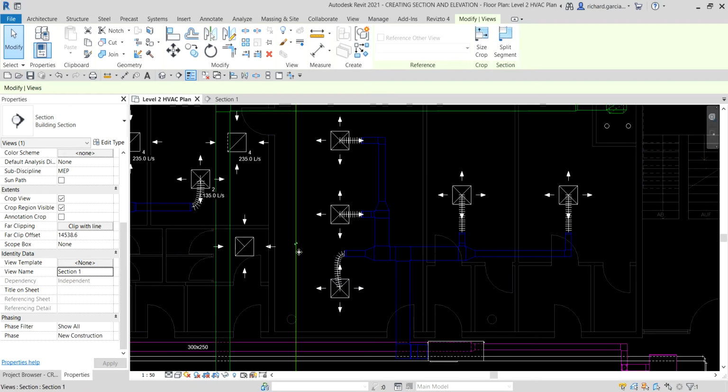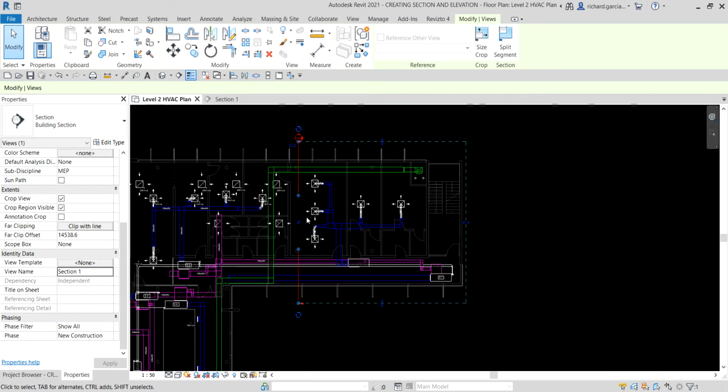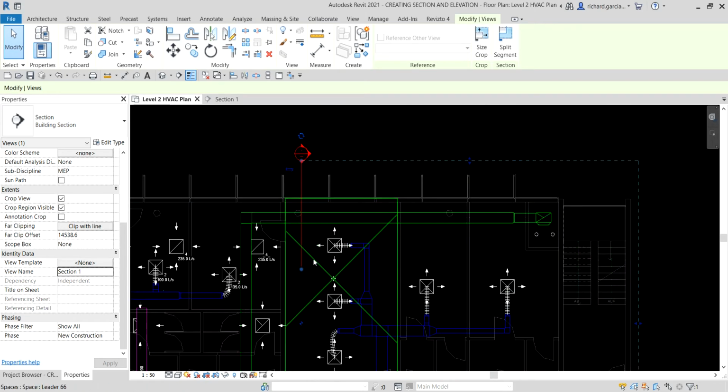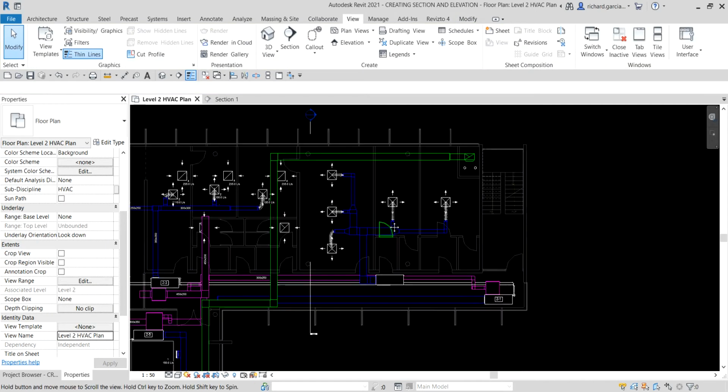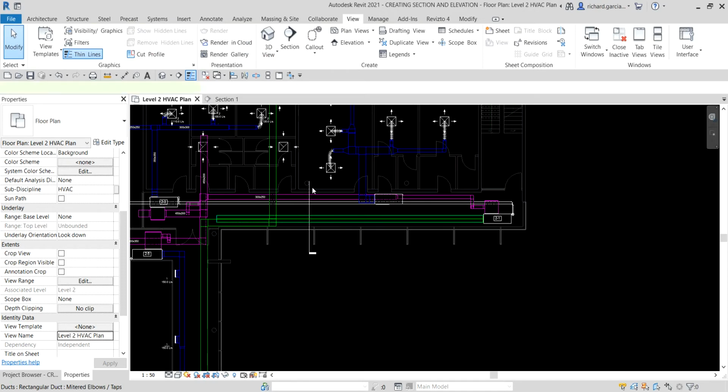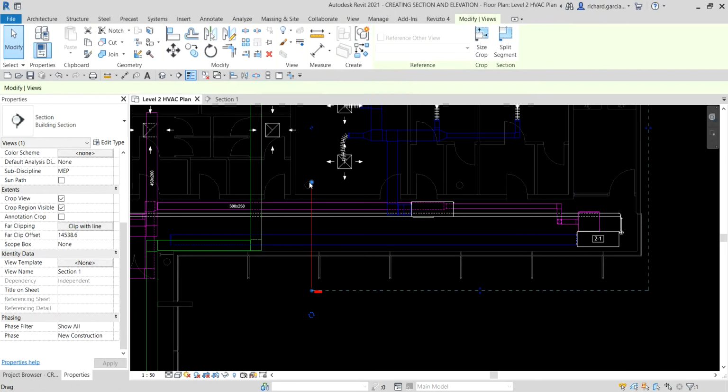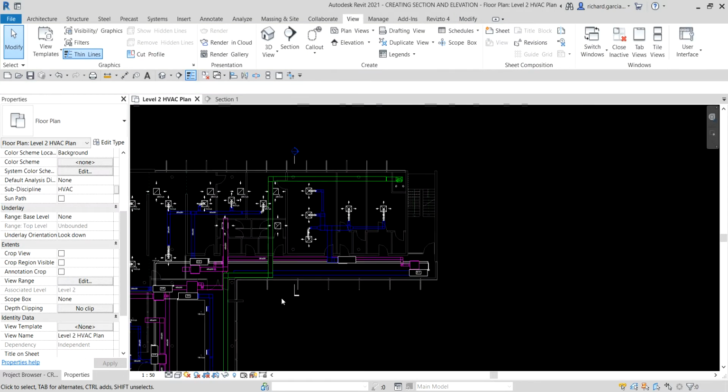Okay? Now, another thing that you may want to consider is you want to tidy up your section. So you can actually break that. Okay, it will create a gap. You see there's a gap in the segment. If you click this icon here, it will create a gap. So usually when I create a section to tidy up, I just create a gap and then I adjust like that. I do not want my section line to be overlapping an element, okay, so that it's tidied up, right?